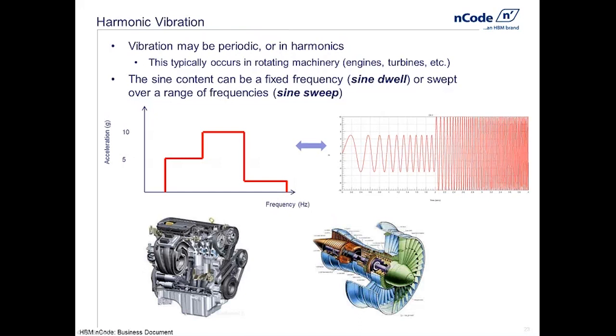So let's say it's on a dyno and there's no gas, no combustion inside of it. It's going to rotate, and probably because of imbalance or valves closing or something like that, we'll get stress cycles that happen once per revolution, maybe twice per revolution. And it's relatively easy then in this, what we call harmonic case. It's relatively easy for us to understand fatigue cycles, right?